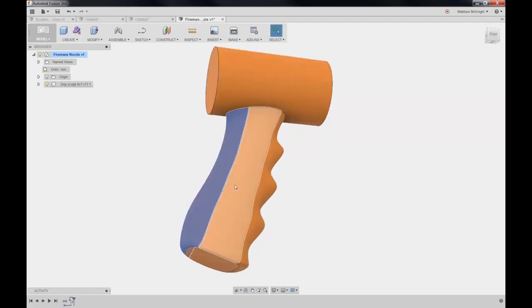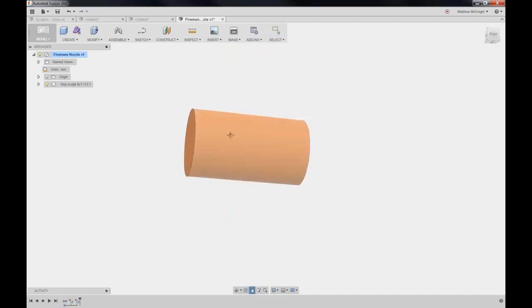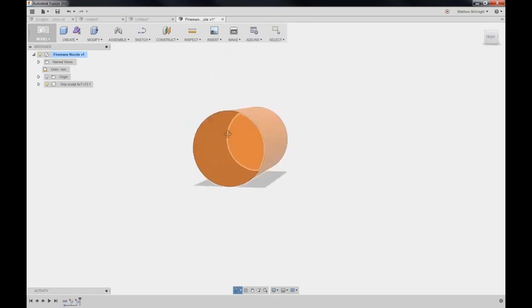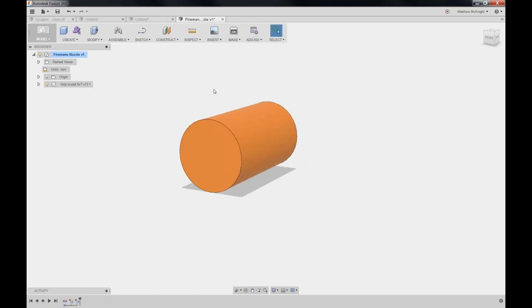So I can select, say, all of these surfaces now to save me going around to the back of the face and choosing the rear face. I can just simply select it using this select other command, and then we'll hit delete, and you'll note that we've quickly and easily deleted the handle and retained is the solid geometry associated with the top of the part. Now we're going to use this as a basis for then creating a new handle that we want to. So maybe we want to modify the existing handle and create a variant of the design.